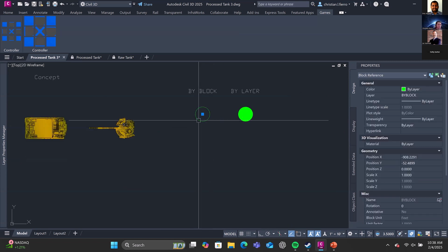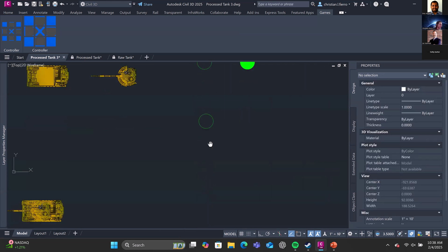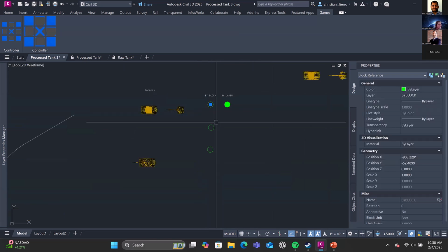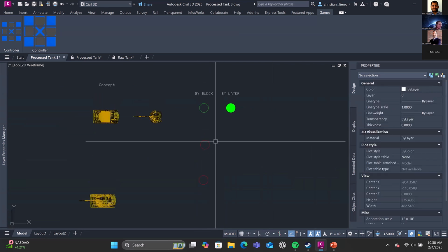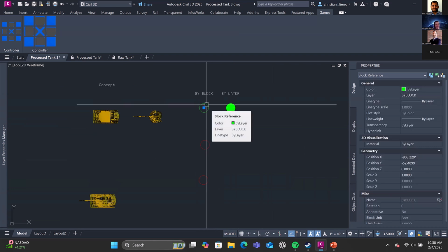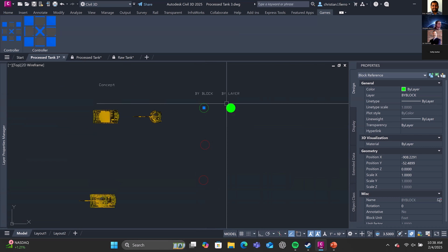Instead of creating a specific object style to handle this, right? Because that's again creating more object styles for this purpose. We can simply create object styles by building them on a by block function. And then whenever we go down the line of, let's say, existing and proposed and revised or whatever the case is, we have the flexibility of individually selecting these and making these red while still having the same layers, same object styles, and same block count.